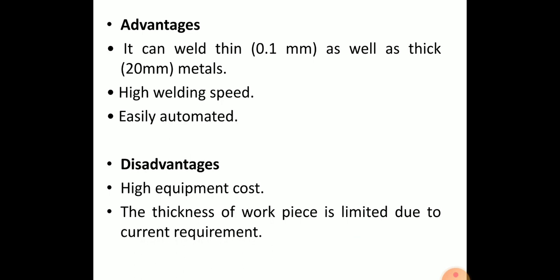Heating of the workpiece is confined to very small parts, which results in less distortion. No filler rod and flux is needed. It is possible to weld dissimilar metals as well as metal plates of different thickness. Semi-automatic equipment is available. There are no consumables used in this process except for the electrical power and relatively small electrode wear. As a result it is a very economical process.